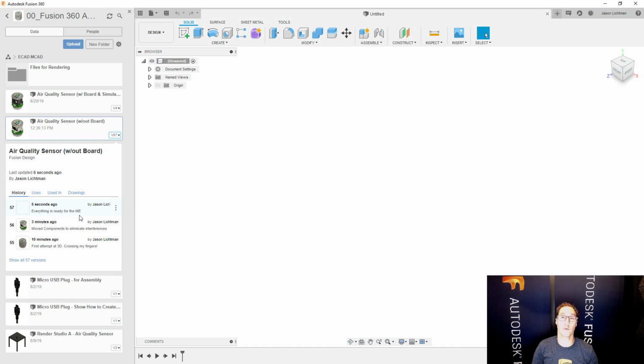As long as you, as the Fusion 360 user, invite the Eagle user to your project, then the Eagle user is going to be able to see that project in Fusion on their Eagle side. Well, that was confusing. Let me say that again. The Eagle user is going to be able to connect to the Fusion 360 files through Eagle and be able to push those 3D models. Now you might, by the way, just as a little future heads up, want to have Fusion 360 even as the electrical engineer, because you'll be able to make 3D models of your custom components and use those 3D models so that when you push it to Fusion, it'll come in with the right 3D model.